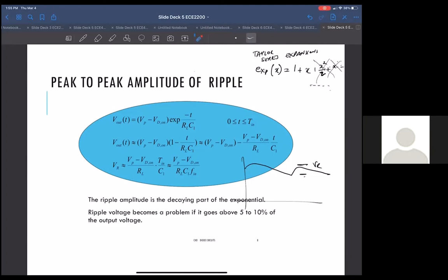And as your capacitors get bigger, they tend to actually have their own inductance and resistance. They tend to ring and have all sorts of problems. So big capacitors are something you want to avoid from a size point of view.